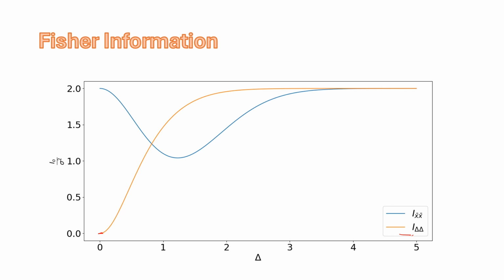still estimate delta. But it turns out that the Cramér-Rao lower bound will be much greater than the width of the impulse response. And so we know, of course, that if there are 2 point targets, they're not going to be separated more than the impulse response. So if the Cramér-Rao lower bound is bigger than that, then it really tells us that we don't have the ability to estimate or determine that there are 2 point targets and estimate their separation.